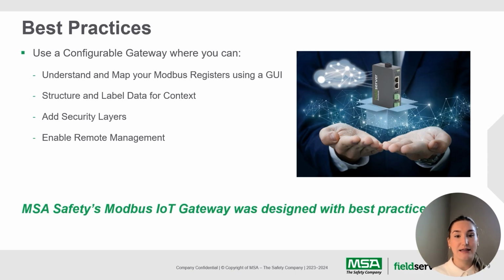Many gateways let you apply tags, units, and JSON formatting for outgoing data. If you're using OPC UA, you can even apply full object models. This makes your data easier to integrate with SCADA platforms, cloud analytics, and digital twins, and avoids a lot of downstream confusion.